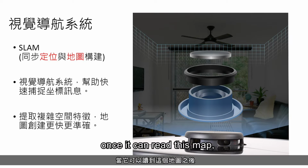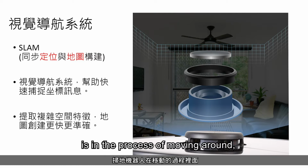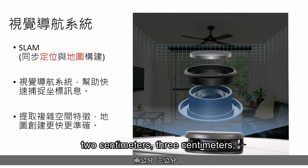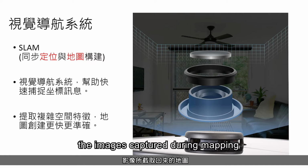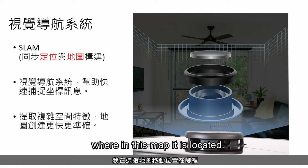For the second thing, once it can read this map, the second is localization. When a sweeping robot is in the process of moving around, it will know that it has moved 1 centimeter, 2 centimeters, 3 centimeters. Then it compares the images captured during mapping to serve as image variability during motion. This way, it can know where in this map it is located.